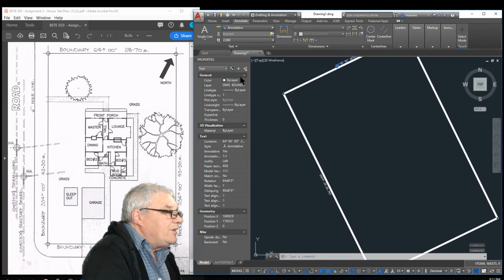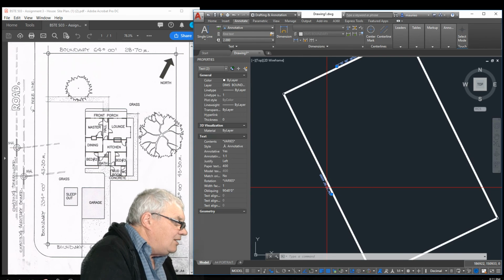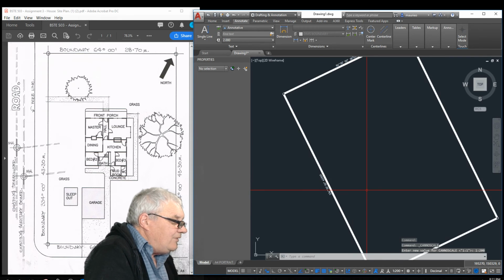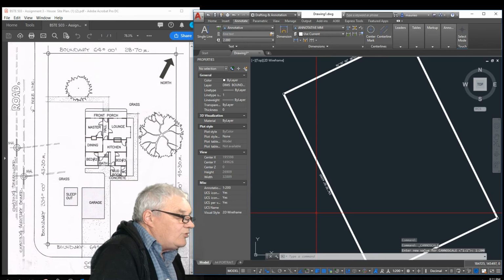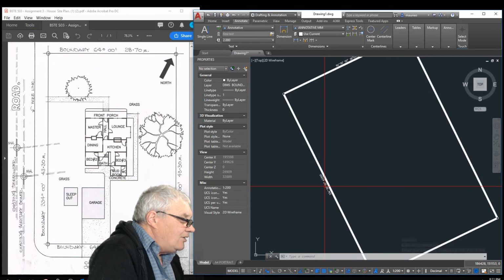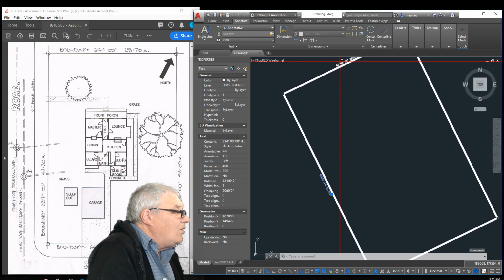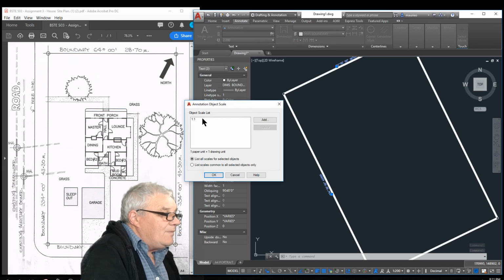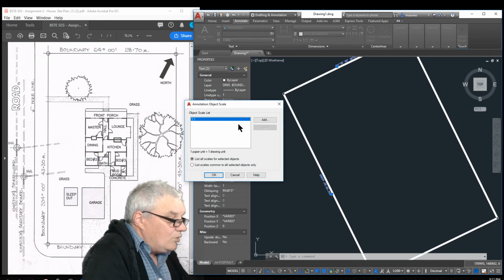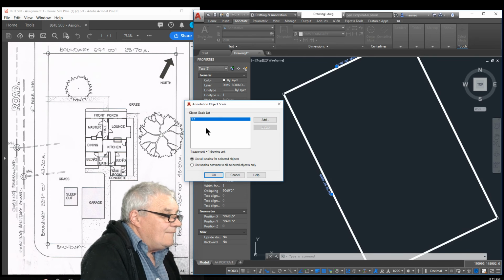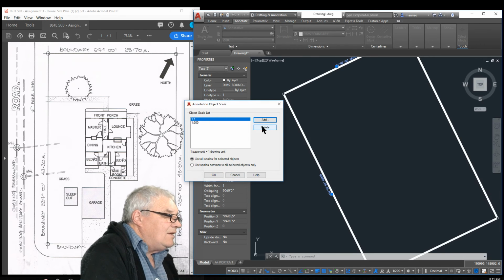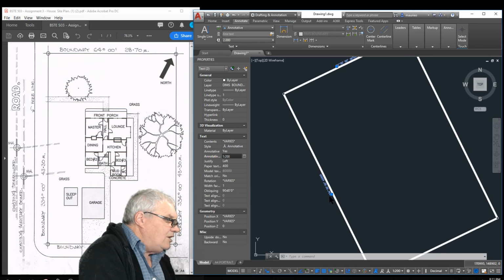I've got the individual picking, so I changed that to model space, but in model space it needs to have the annotation scale here, which is that one there. Otherwise it won't show. So both of these here should need to be 1 to 200. So we'll delete or add 1 to 200. Okay. All right.